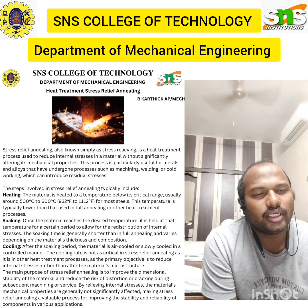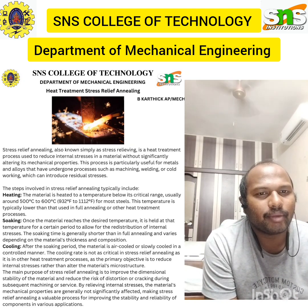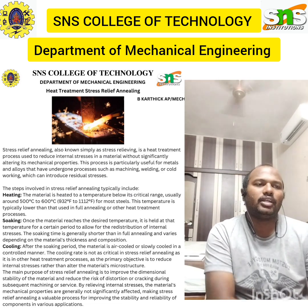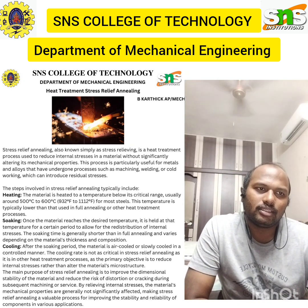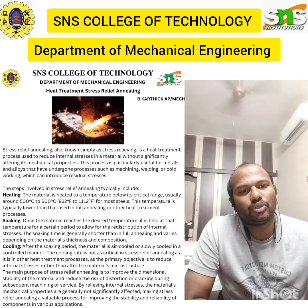Stress relieving annealing is a heat treatment process used to reduce the internal stress within the material, typically metals. These internal stresses can arise from various mechanical processes such as casting, welding, machining or cold working. Stress relief annealing helps to improve the dimensional stability of a material, particularly metal, and reduce the risk of distortion or cracking during subsequent processing or use.